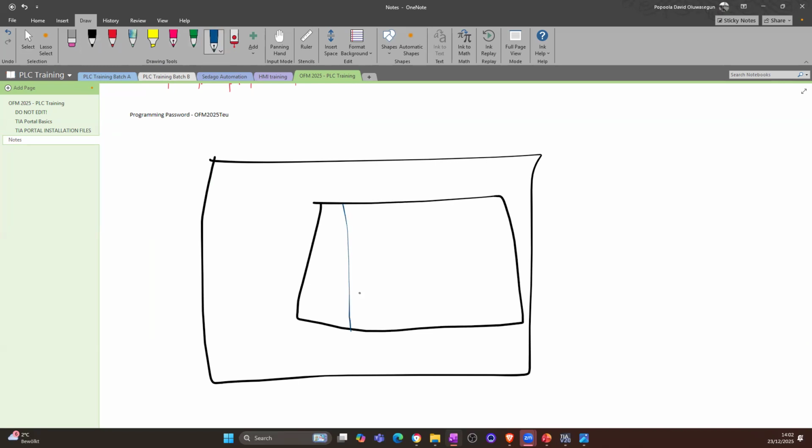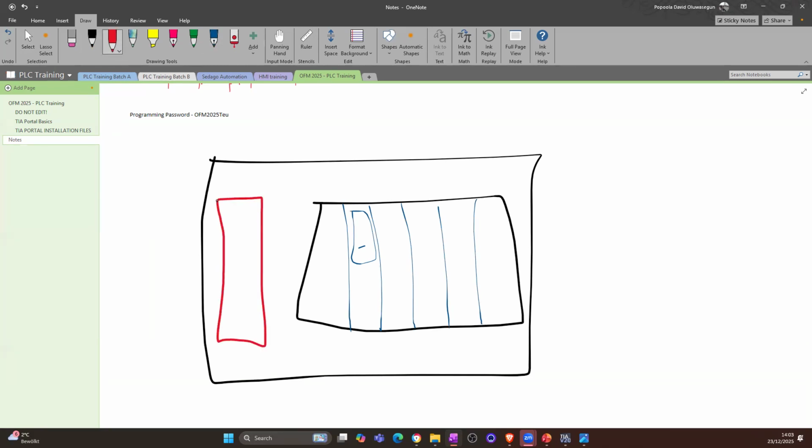You have the PLC here, the PLC itself, and then, for example, you have other modules. The first power supply, which is the power module, the 24 volt power module, can sit anywhere in the panel, can also sit on slot 0.